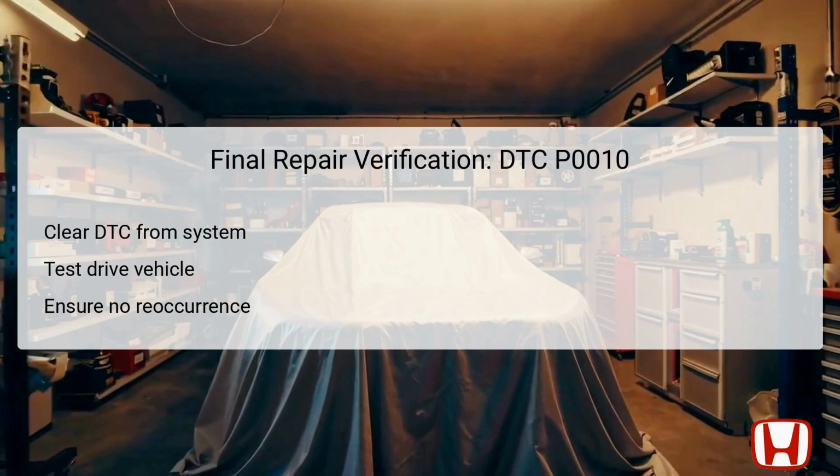Once the necessary repairs have been made, a final verification step is crucial to ensure that the issue has been resolved. The first action is to clear DTC P0010 from the vehicle's computer system. Clearing the code resets the system and allows for fresh readings.